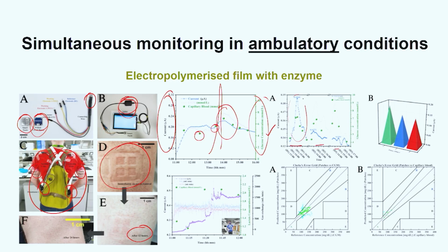The current values that you get on day 1 go down significantly on day 2 and day 3. Anybody? What does this mean? Is it due to sensor fouling? There's a lot of things going on there. Degradation of sensor. Anybody else? So would you call it degradation of sensor, or degradation of sensor performance, or contamination of sensor? How would you want to define it? Everything together. Good. It's actually the right answer.